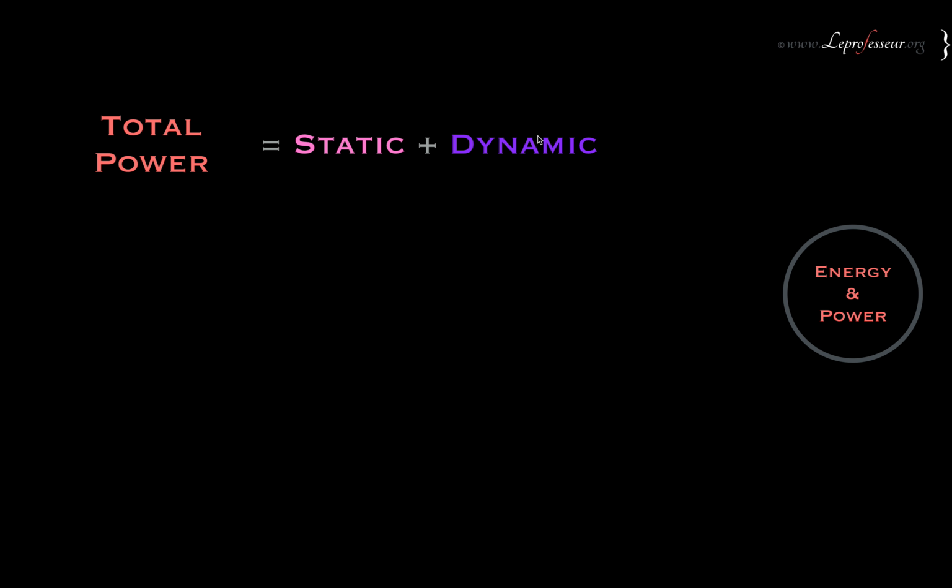We can somehow think about controlling the dynamic power: increasing the clock frequency, decreasing the clock frequency, and whatnot. And capacitance: we can see how much the extracted capacitance of this net is, and how we can reduce it. So we can do something about the dynamic power, but we cannot do much about the static power.